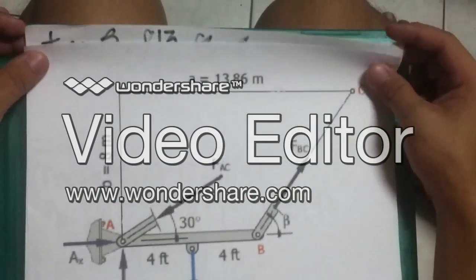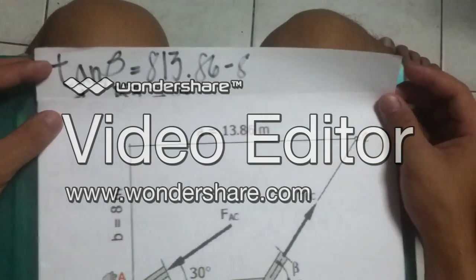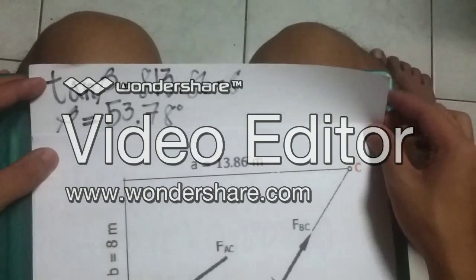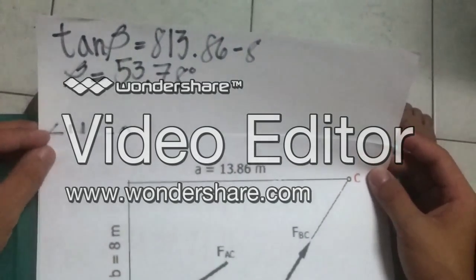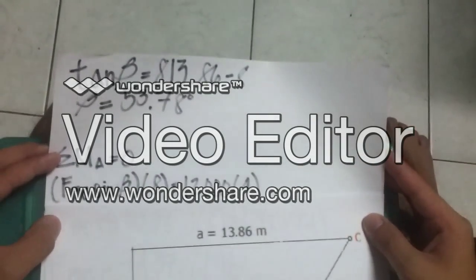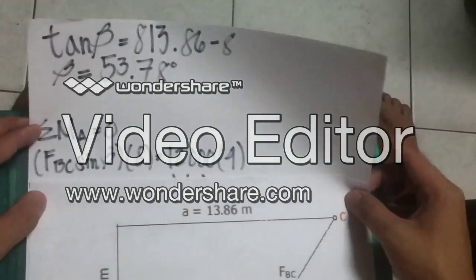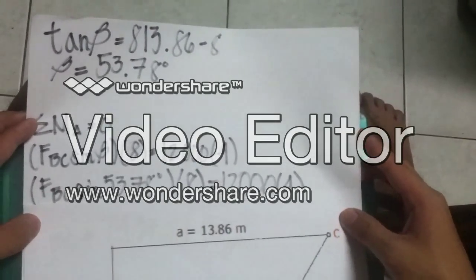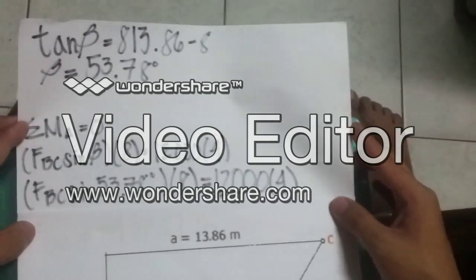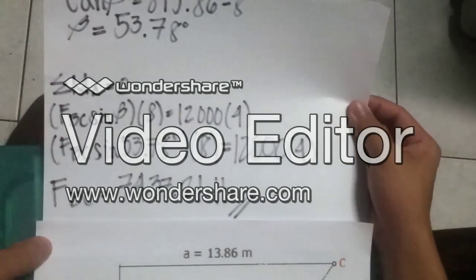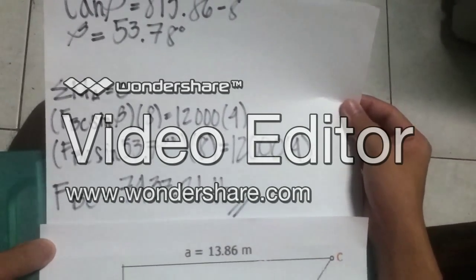To find the force BC on member BC, first we must find beta. Tangent beta is equal to 13.86 minus 8 over 8, then beta is equal to 53.78 degrees. We use again the moment at A, and the summation of moment at A is equal to 0. Then force BC sine beta times 8 is equal to 12,000 times 4, and substituting beta, force BC sine 53.78 degrees times 8 is equal to 12,000 times 4. Lastly, the force BC is equal to 7,437.21 pounds.